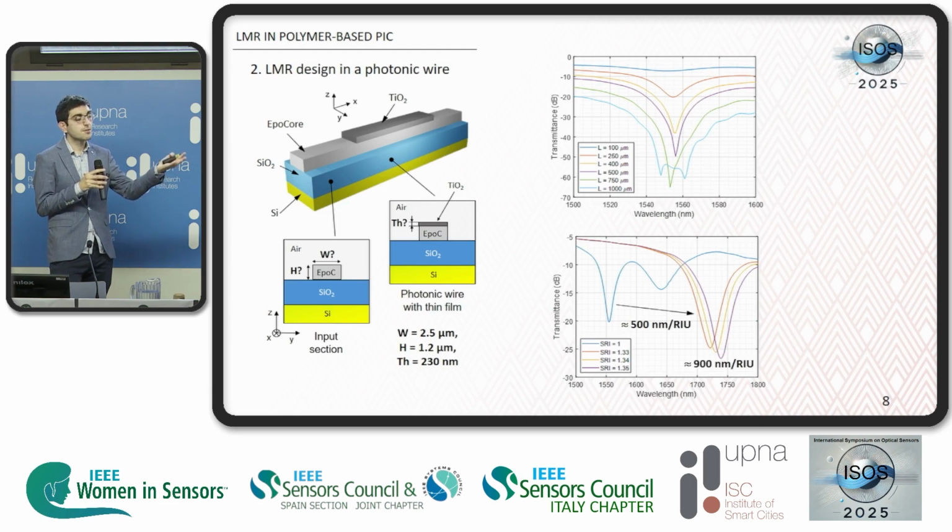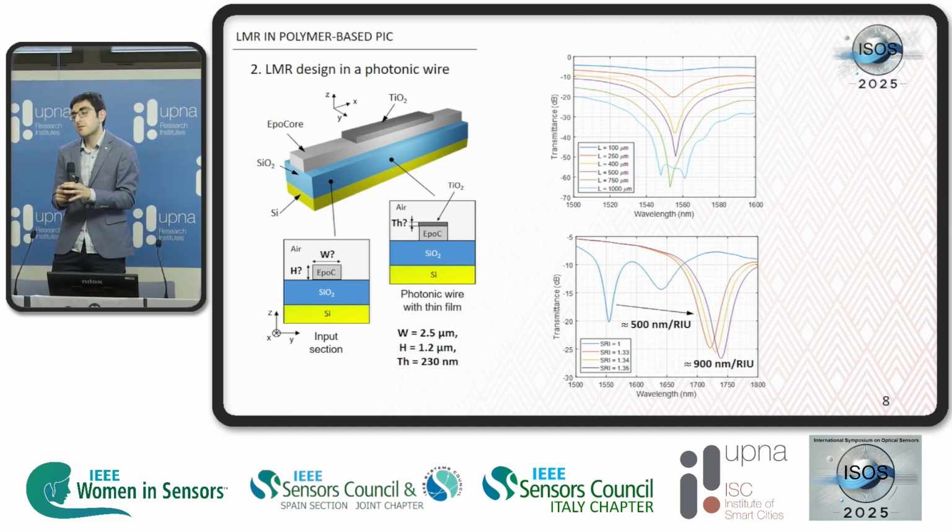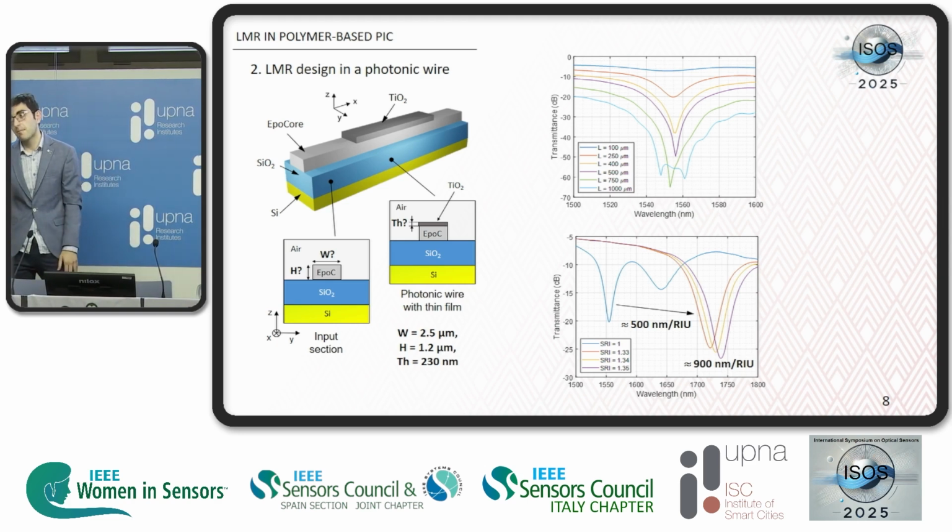This is only a simulation. From this simulation, it's obvious that if you wanted the same device to work in air and in water, the grating coupler is not going to be a good solution. Of course, from what I have seen, in integrated photonics, most designs are either done to work in air or directly to work in water. So if you, for example, did a design to work in water, you could be in this area and you could design a grating coupler to work on this area and it would be enough, and you would forget about this part. But as we usually give a rough number of sensitivity between air and water, I performed this simulation. But probably for most applications, it's going to perform well only using a grating coupler.